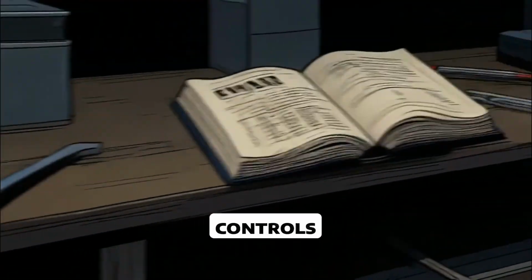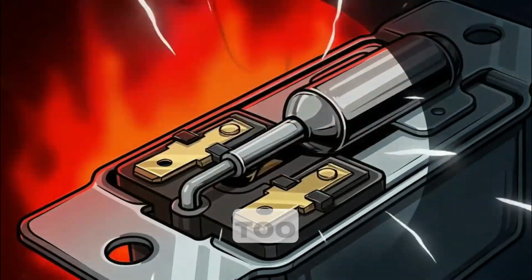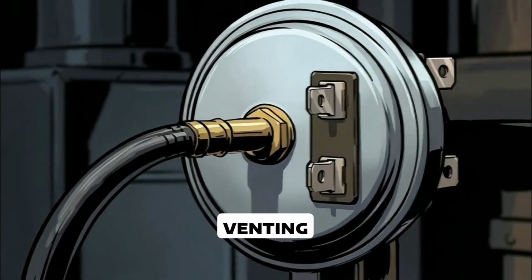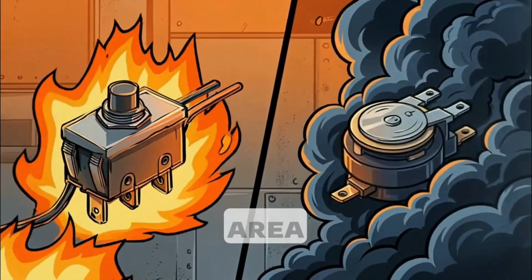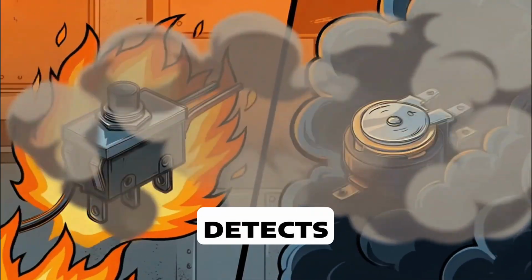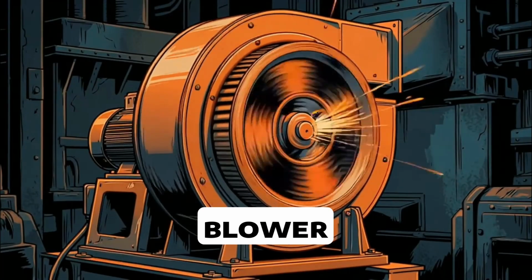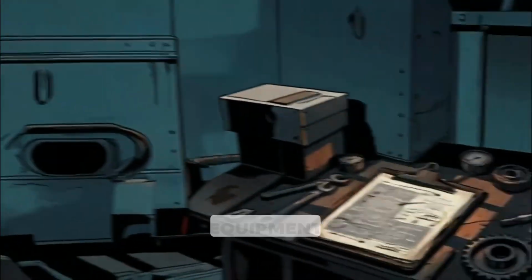Now, safety controls. A high-limit switch shuts the burner off if temperature gets too high. A pressure switch proves inducer airflow and venting conditions. A rollout switch trips if flame escapes the burner area. A spill switch detects vent spillage. A fan control starts or stops the blower at proper temperatures. These controls protect both people and equipment.